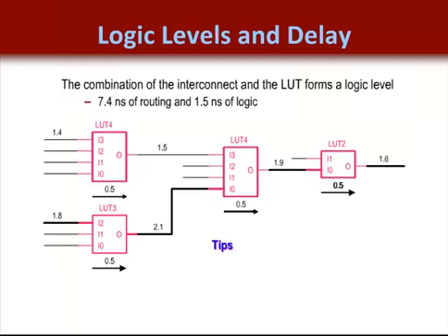Always keep in mind that your synthesis tool will decide how your logic equations will map to the LUT architecture. So it will decide how many LUTs and how they are connected together. So depending on your coding style, the synthesis tool might choose to code some logic in series, as in this example, but depending on the type of component you're building, your synthesis tool might be able to build that logic in parallel. Fortunately, synthesis tools are getting better at mapping logic to parallel LUTs.